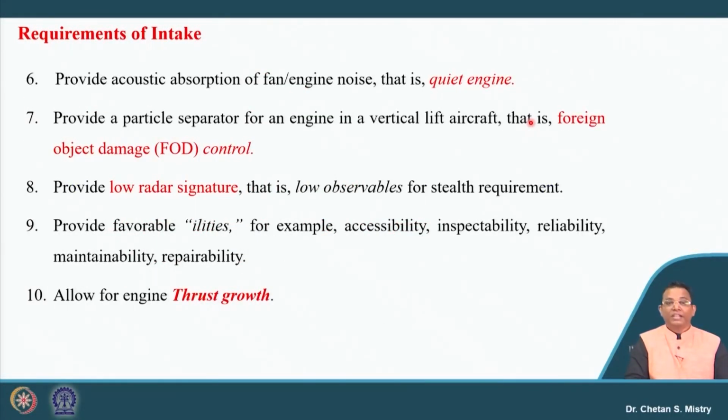It is not ending there. Now the situation is, one of the restrictions these days is the noise generated. So it should not produce high noise. So we need to have an intake that will give a quiet engine. Now suppose we consider a military application, or maybe our helicopter engines, for that maybe foreign particles will be ingested inside the engine. So it should avoid that kind of situation.